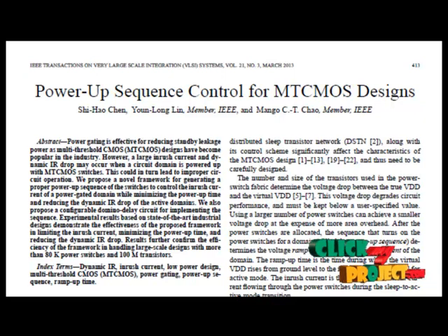While power gating has been adopted for use on asynchronous circuits, most of these efforts involved direct applications of synchronous techniques to asynchronous systems. As such, the unique capabilities of asynchronous circuits have not been fully leveraged in the context of power gating. Many asynchronous circuit families are robust to a wide range of supply voltages, ambient temperature and power variations. We exploit this robustness in the context of power gating to enable a zero delay wake-up scheme for pipelined computation.